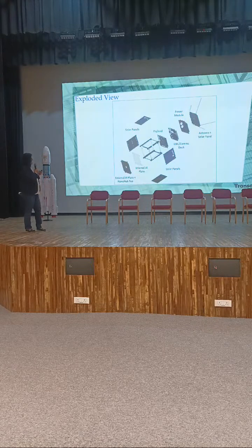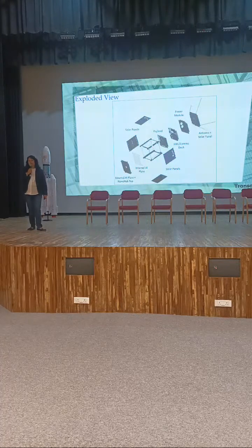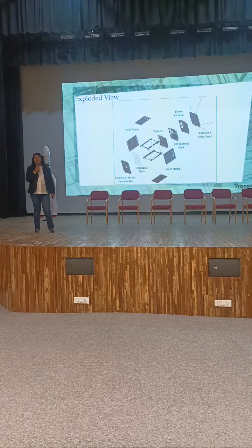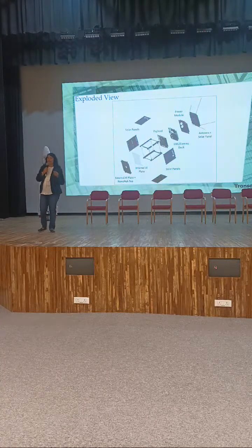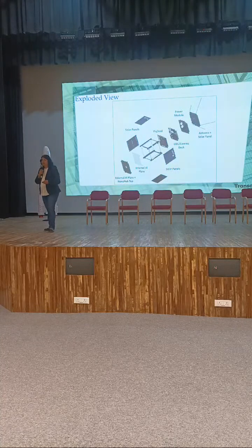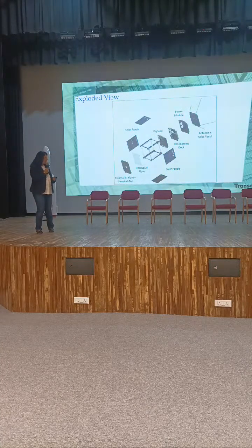And then, depending on the type of payload data, the communication frequency or the communication band which is required, and the data rate at which the payload data has to be transmitted to the ground station, are determined.